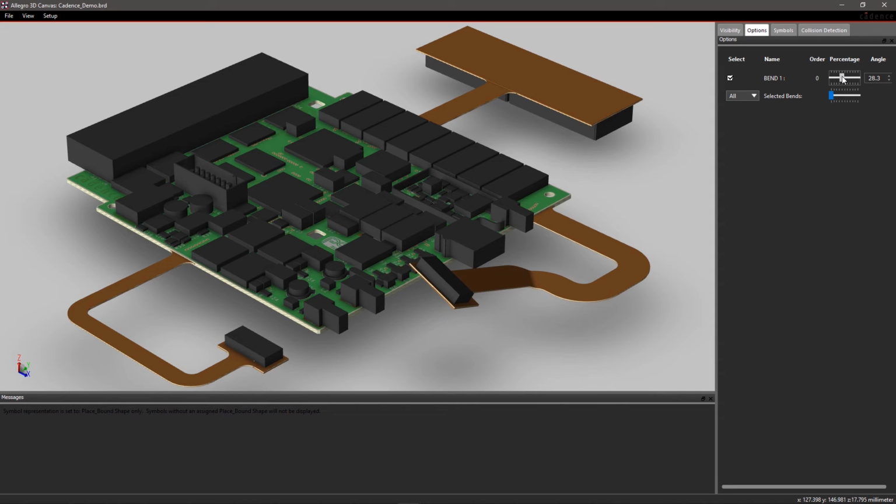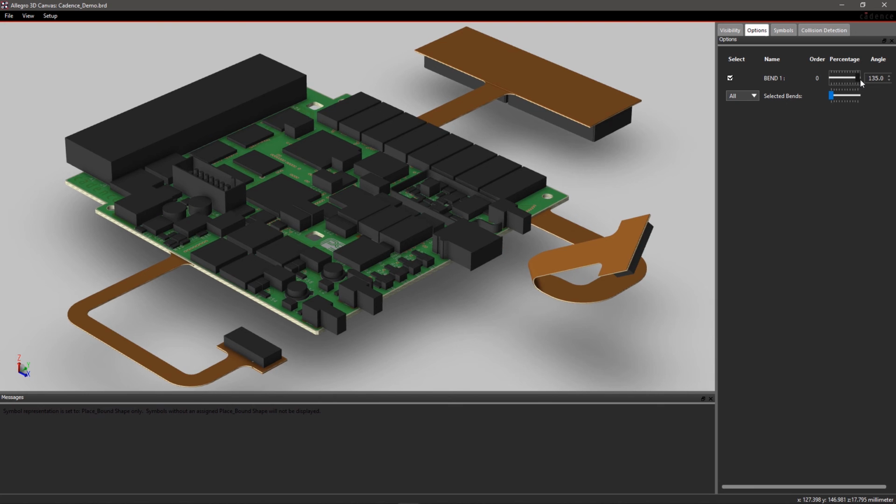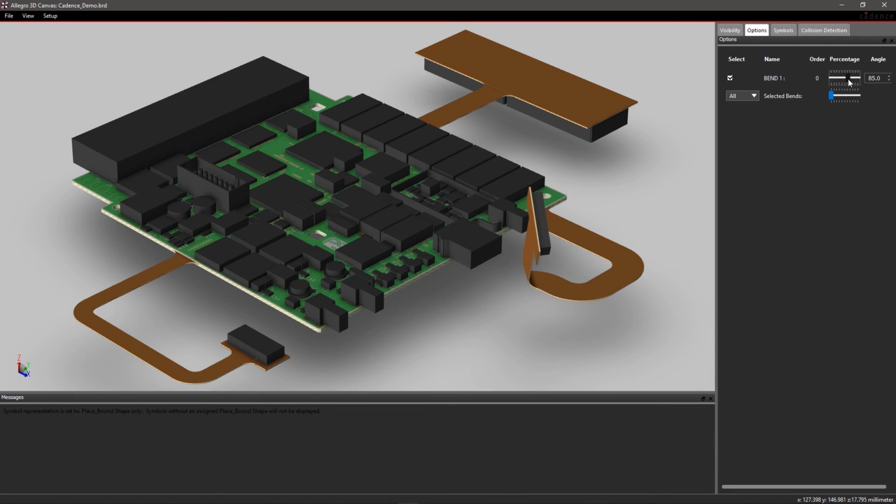Notice that, along with defining a different stackup and materials for the flexible part of your design, specifying the bend details accurately communicates to manufacturing where the bending and flexing should occur. Similarly, you can create bends in other flex areas of your PCB and visualize the results in 3D. With OrCAD, it's easy to create bendable areas in your rigid flex design to fit your final product.